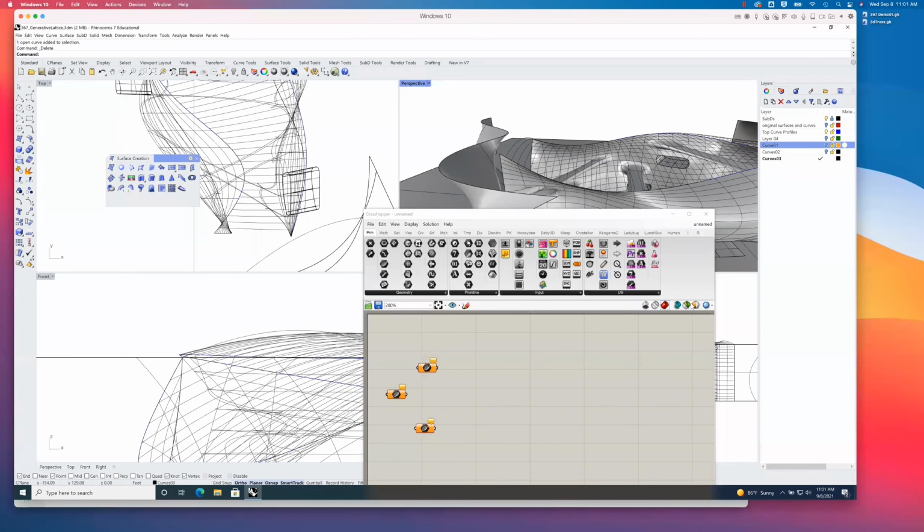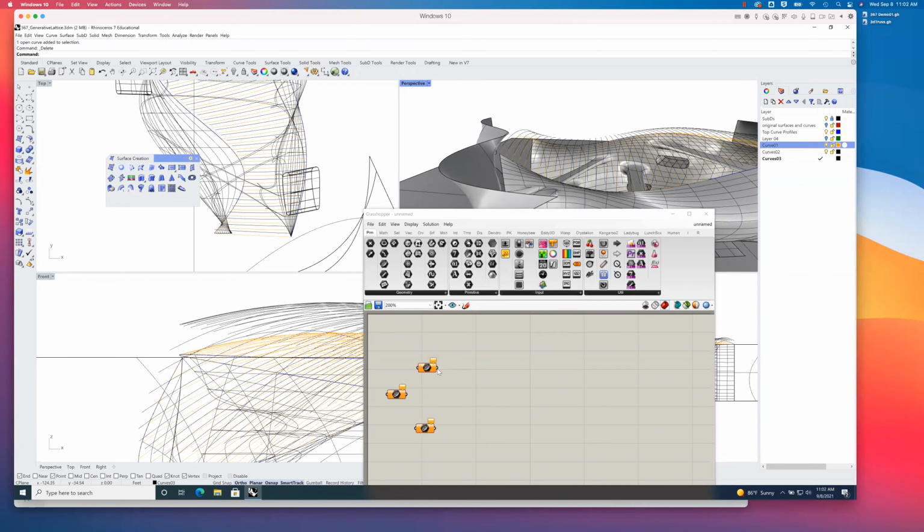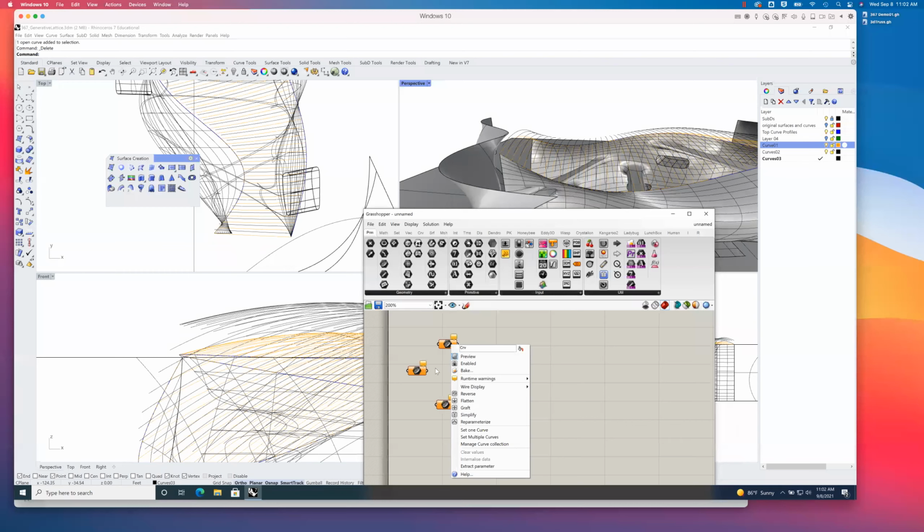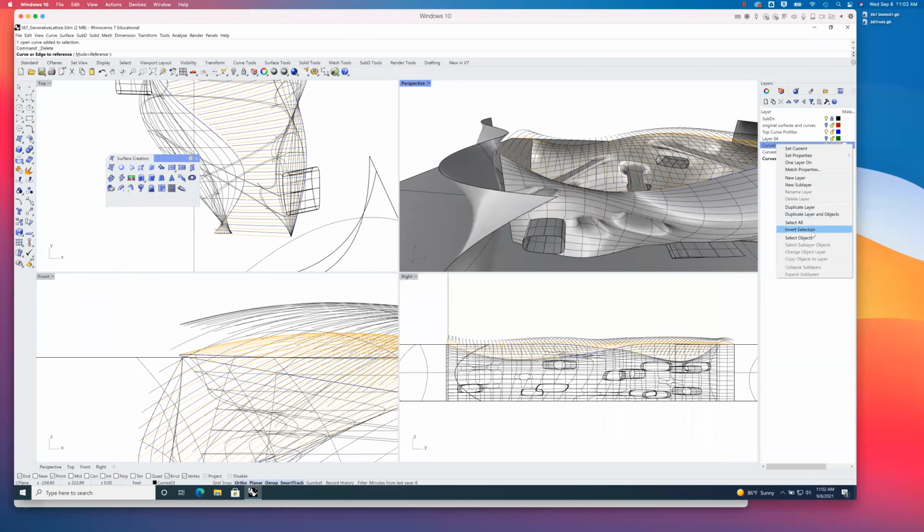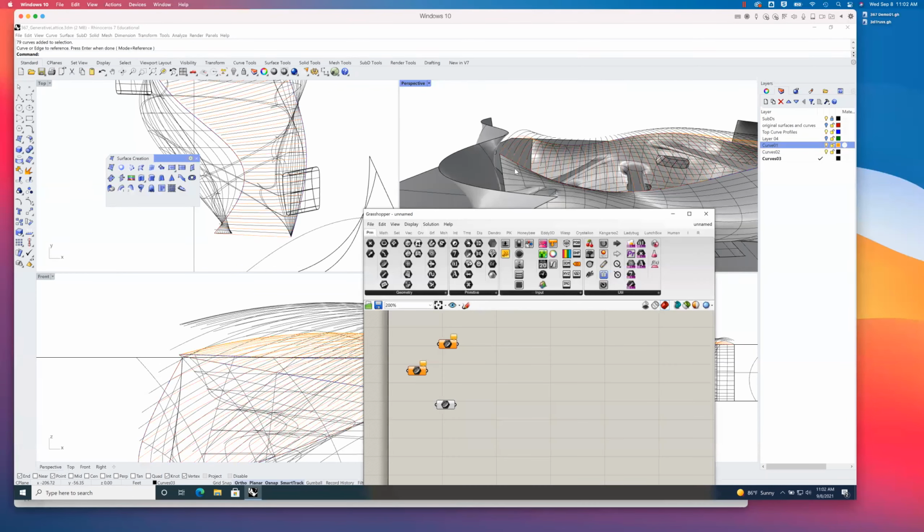All right. So I'll turn all of these on at once. You'll see, I think, what I'm going to do here. I'm going to say, okay, these will be the bottom left, set multiple curves. In this case, I'm just going to go curve 01 and say select all the objects on layer curve 01. Hit enter.